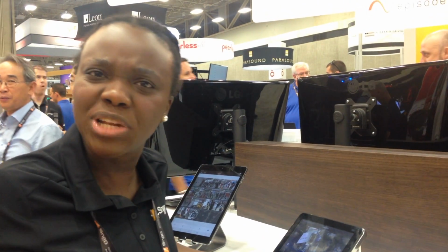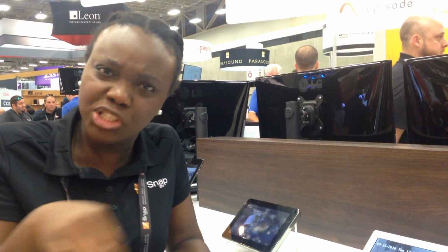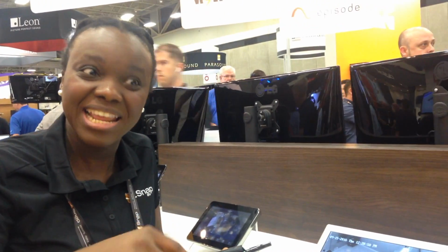And Overseer is always really great to have. And remember, on these new IP cameras, in the past we had issues where people were worried about false positives in motion. But these new cameras have wonderful new features like line crossing and box intrusion that help reduce the false positives. An example of line crossing: you draw a line on your driveway. When someone crosses that line, it's an event.